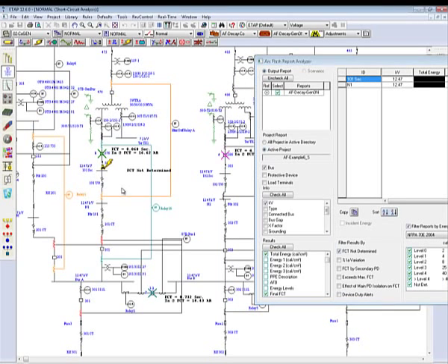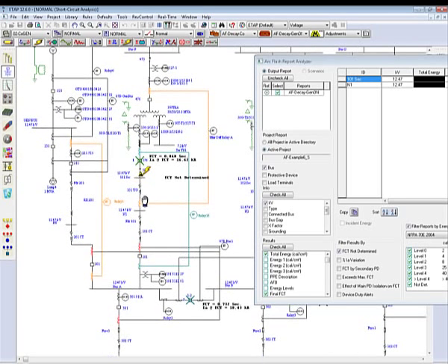Notice that the branch that the generator is feeding is not being de-energized. In ETAP, the generator will be sustained at steady state, and it's required for it to be de-energized in order to fully find the fault clearing time. You can also see and inspect that there's only differential set up and no overcurrent device here in this first level to de-energize it.